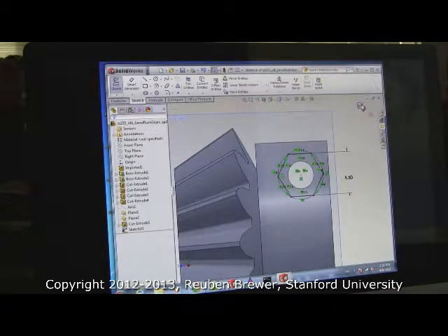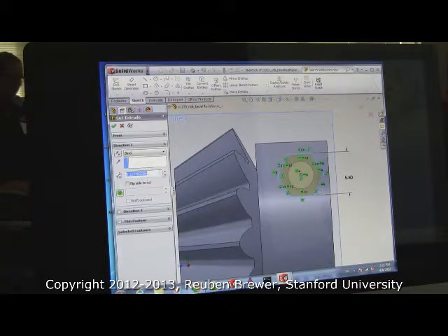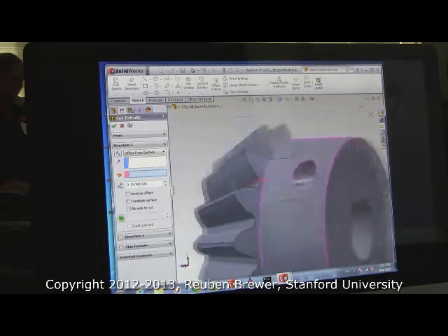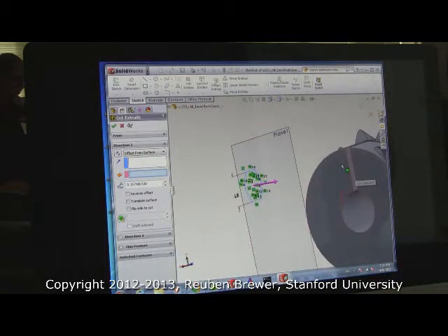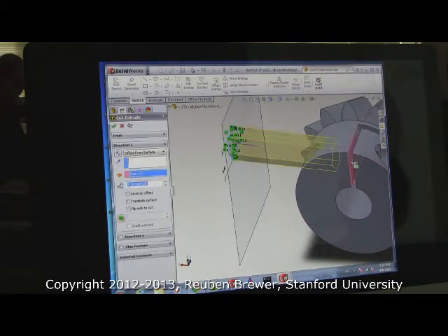Okay, go ahead and press the purple pencil thingy. And we're going to do the same thing as last time. Offset from surface. And select the nearest surface, this one right here. And it's going to be 4 millimeters.